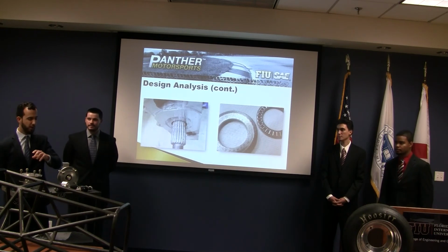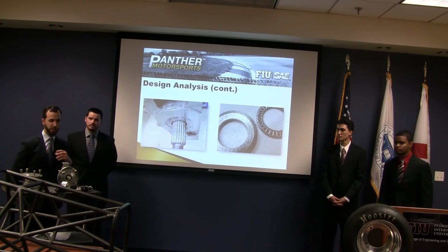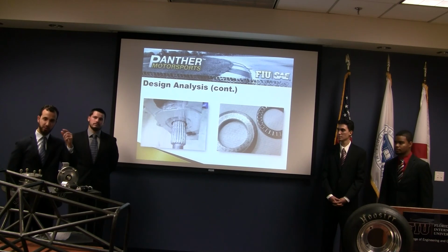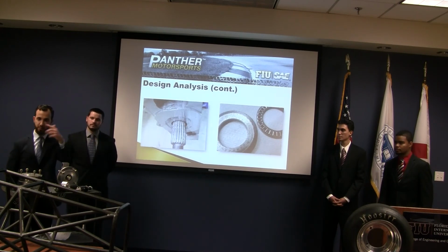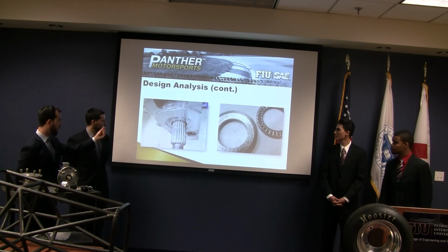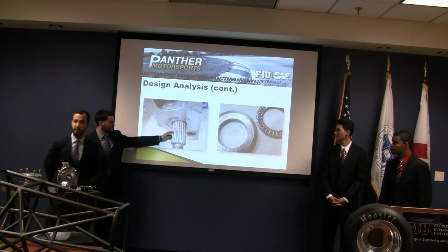Because it was improper translation of forces through the bearing. You want to translate the force from the inner race to the ball bearing to the outer race. We were just translating it through everything. And that's why you see the scrap material on there.